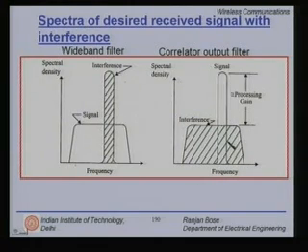So, this shows that a strong interference to a weak signal, once despread, gives you a strong signal and a weak resultant interference. In fact, this is the processing gain. Very simple technique, but very effective. What it also tells me is that I can increase my processing gain more and more, thereby being able to handle stronger and stronger interferers or jammers. So, inherently this technique is secure against jamming to some extent.